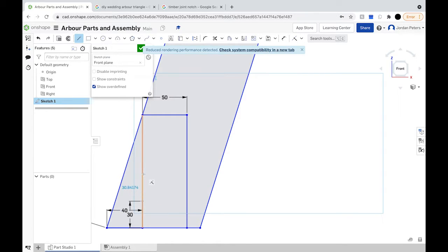It's important to dimension everything because when you go through to make the next part, it gives you a reference point for where things need to be. So if you do an arbitrary dimension, if I just go this number here, then I have to write that entire number into my next part that holds it upright, just in order to get where the circle is.